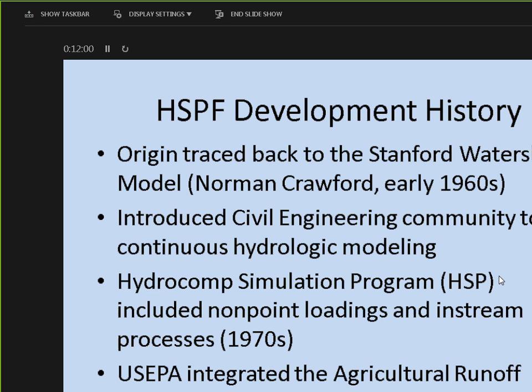And the first thing they tried to do is take that outlet hydrograph and prorate by land area. But that didn't turn out very well, and they realized they needed a model, some sort of tool that would take into account the precipitation patterns, what's going on in the watershed, the cover in the watershed, the soil types in the watershed, and also the configuration of the drainage network. What does the channel look like?